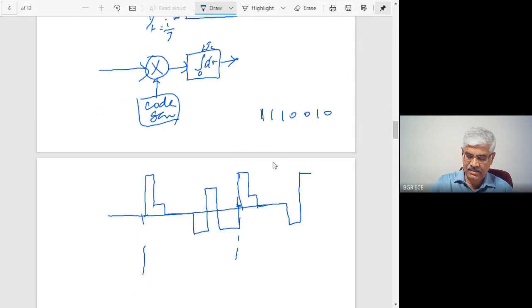Whereas here, if you put a threshold like this, the intermittent value of the autocorrelation will give you a false alarm. So here also it is above threshold, so you assume that the signal has been received. But here also it will give you another alarm saying that another bit has come, which is not correct. Whereas your bit length is only this one, so it has to show only at these instances.